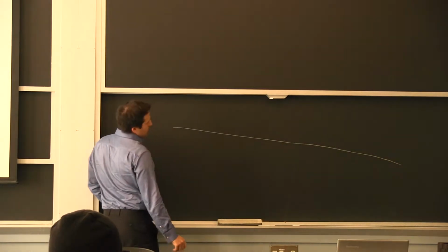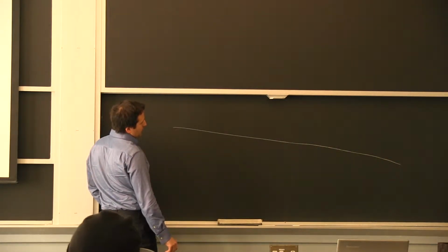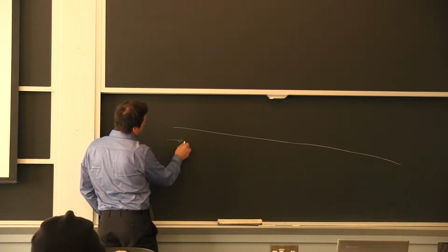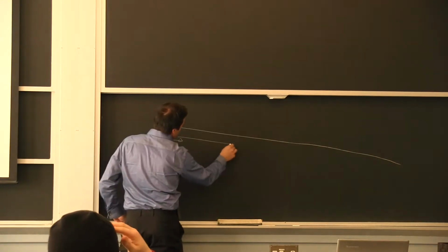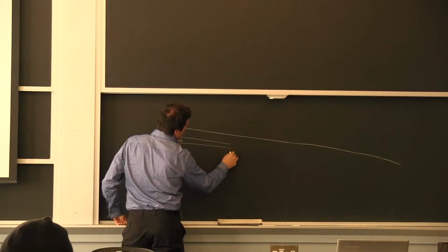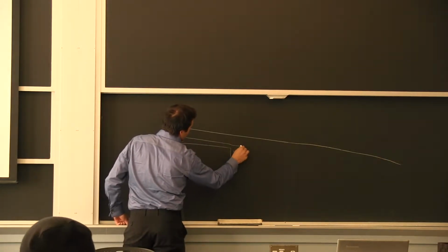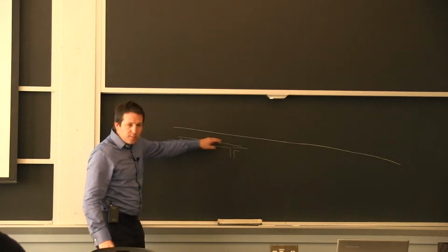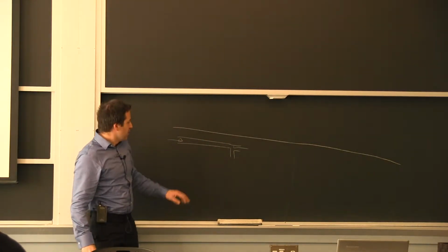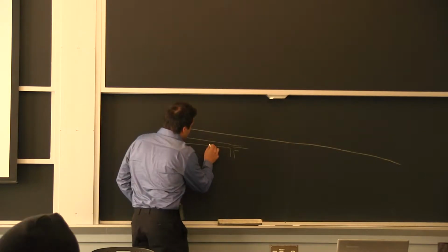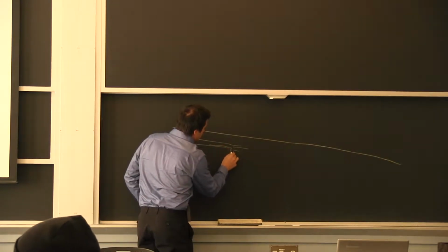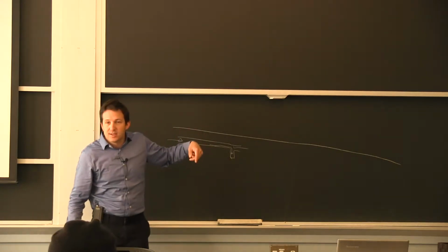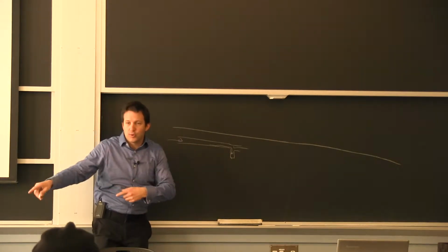You have to think about your supply. So say we're talking about the steam supply going this way, you would want to break it down and then have these legs every once in a while that will collect the liquid. So you have the steam going down the street, and the liquid is getting trapped in these drip legs, and then you turn it into the condensate line. You just turn it over to the other system.